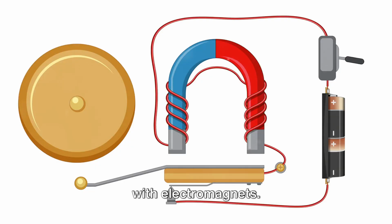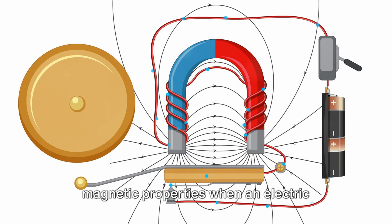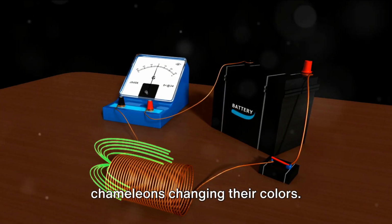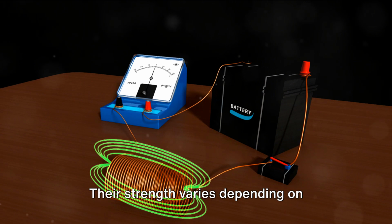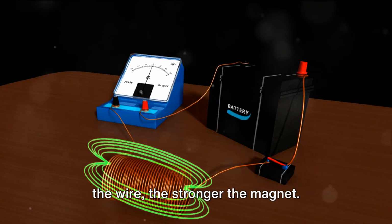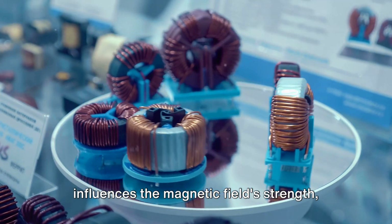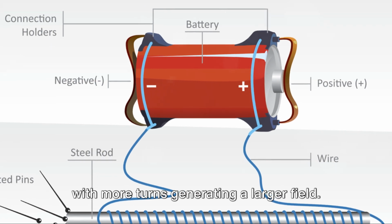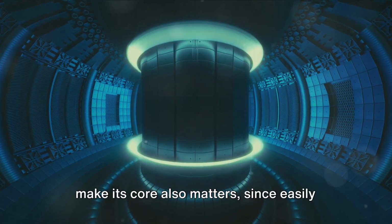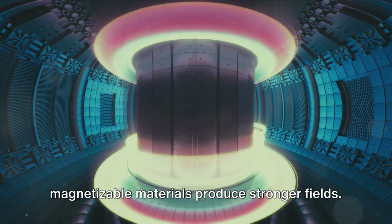Imagine being able to switch a magnet on and off at your convenience. This is possible with electromagnets. These unique magnets only exhibit magnetic properties when an electric current is passed through them, similar to chameleons changing their colors. Their strength varies depending on several factors. The more electric current flowing through the wire, the stronger the magnet. The number of turns in the coil also influences the magnetic field's strength, with more turns generating a larger field. Further, the type of material used to make its core also matters, since easily magnetizable materials produce stronger fields.